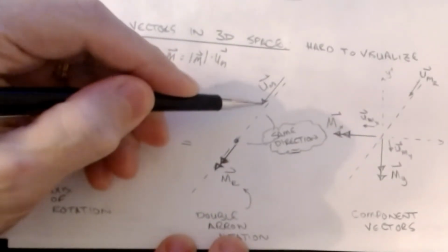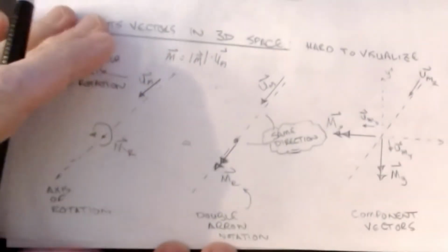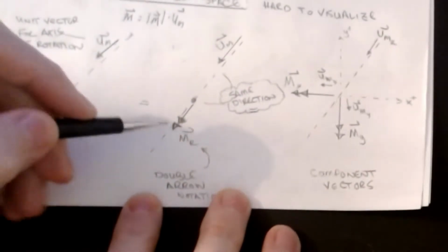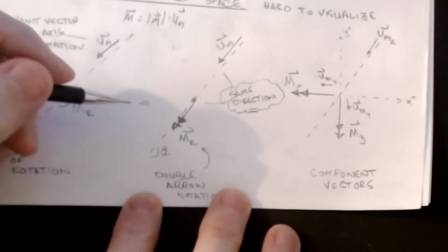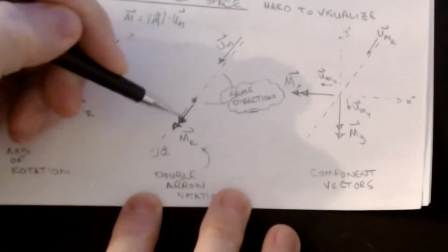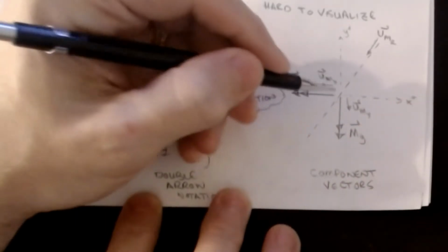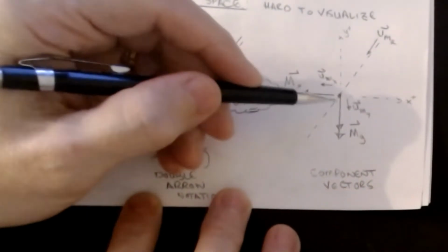And you'll notice that the direction of that double-headed arrow is in the same direction as the unit vector that we had up here. Now, the thing that lets me do that, which I can't visualize on here, is if I draw it this way and say this angle theta is the orientation of that line, well, I can say this is a resultant moment, apply it at the point that I'm interested in, and now I can find the components of this resultant by doing all the same games that you did with forces.